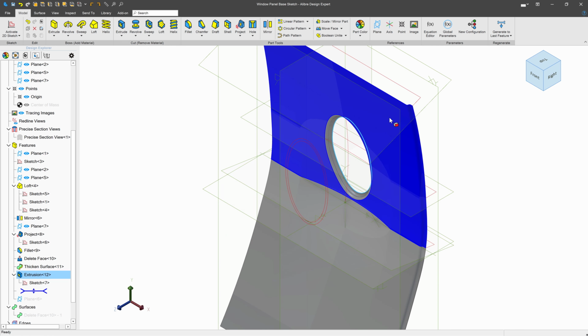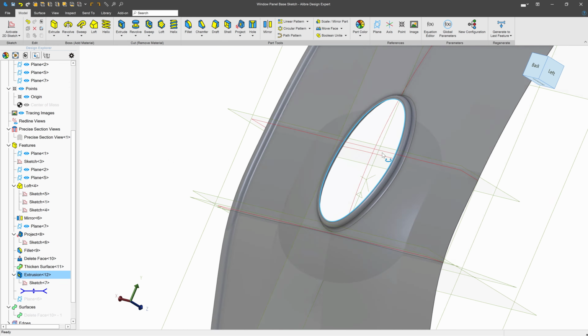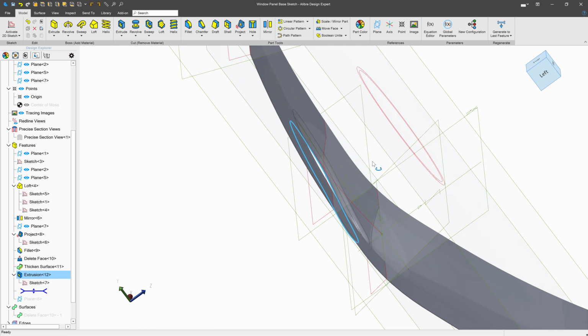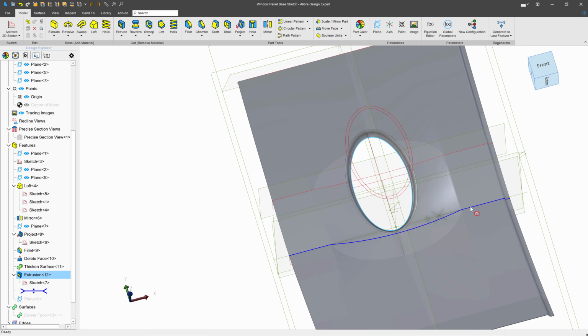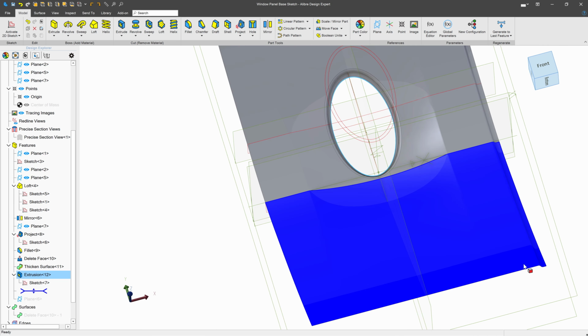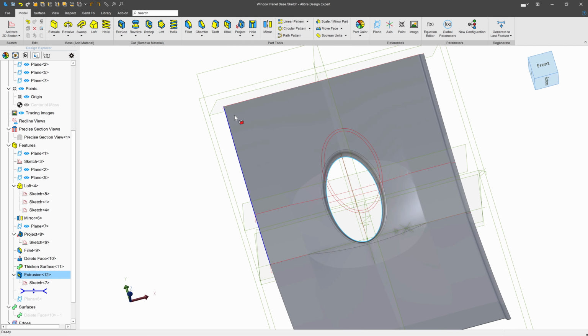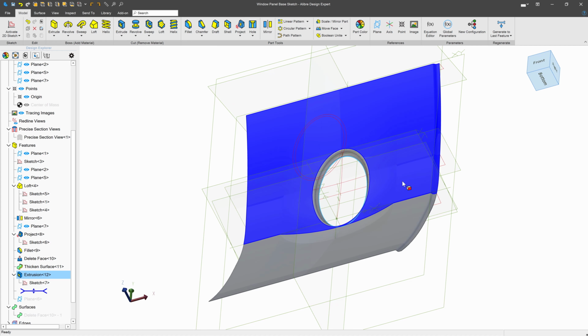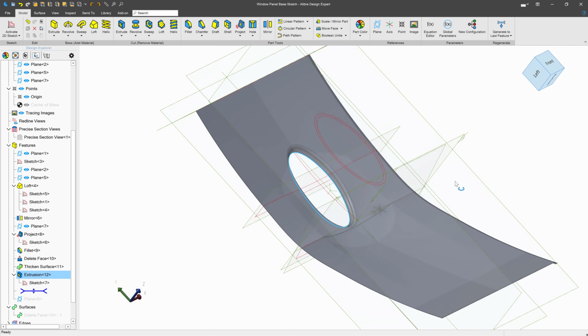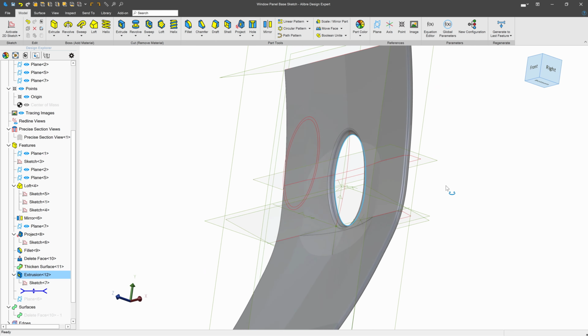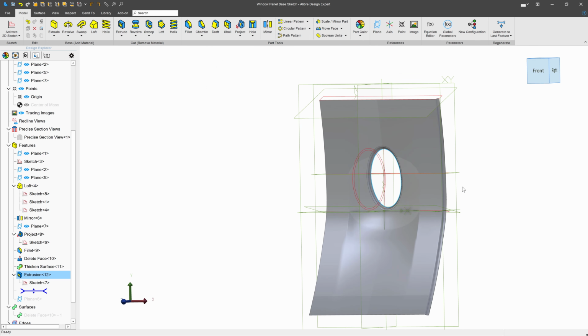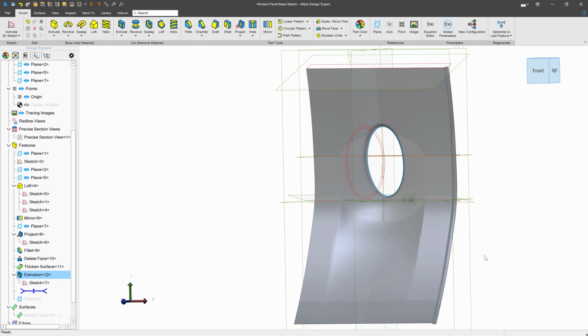And there, we were able to make a panel of constant thickness a lot easier than trying to do it all in one loft. We were able to use sketches in ways that we started completely straight down here. We added a curvature with sharp lines down here, and then back to straight, and that created some crisp lines in our profile. And we saved a whole lot of time than trying to do this all in one loft. We also have two different methods to achieve a constant thickness, and that really helps in the cases when you're going for constant thickness and one reason or another you're not achieving it.